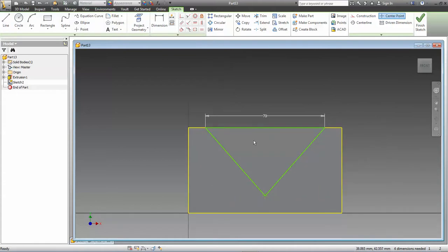Now, the only problem with this is the loft command won't let you loft because it's not really a proper triangle. It's just a series of line segments. Won't let you loft between these unless you close the loop. It's called closing the loop.